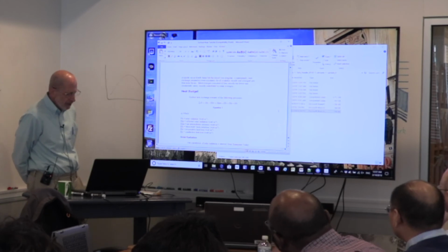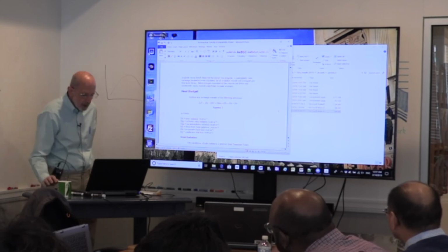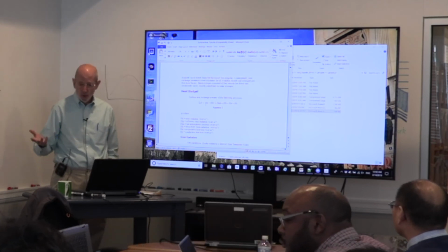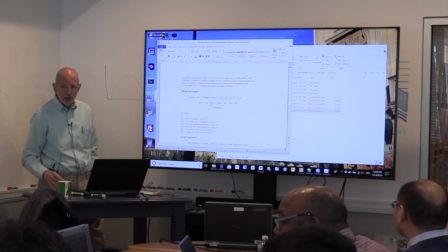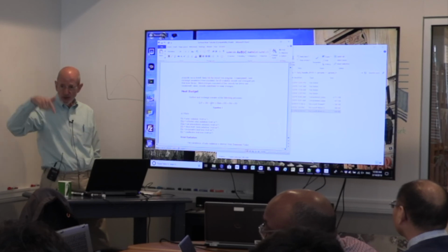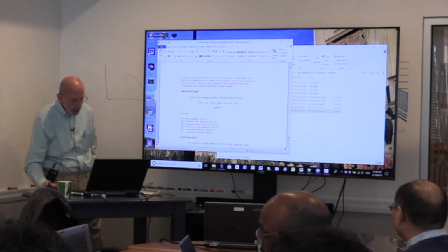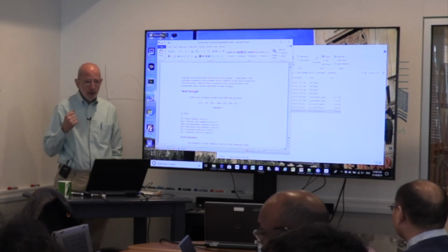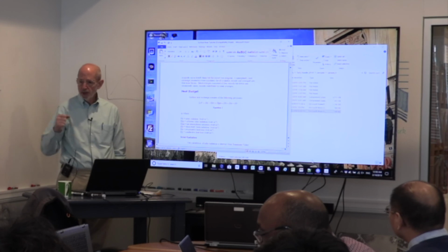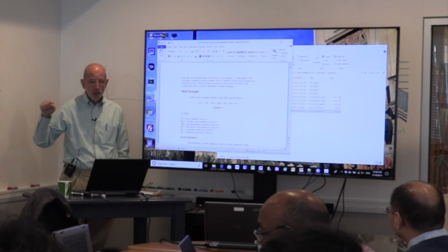Okay, the major thing about this heat transfer, I'm not going to go over every equation, but the elements of surface heat exchange are solar radiation. So the sun shines and it warms up the water. Some fraction of that is reflected back, and this is more or less taken care of. But, you know, it hits the water, some fraction is reflected, some fraction heats up the water. Atmospheric radiation. You think of the sunshine, you think, well, how does the atmosphere shine? But we're talking about black body radiation. The atmosphere has heat, and that creates thermal radiation.